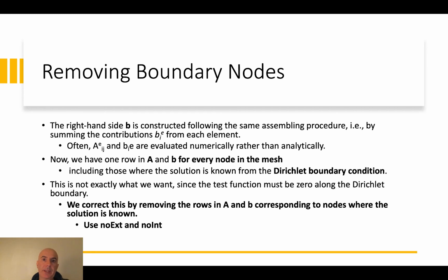One part of our work is actually to define the boundary condition. In this case, we know what the boundary conditions are. We are going to use Dirichlet boundary conditions at the inner and outer boundary, imposing a difference in the potential of 1 volt.